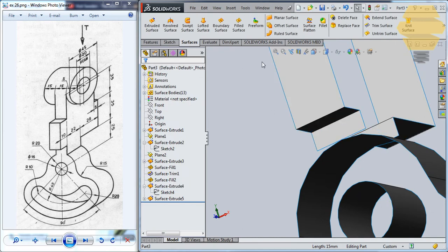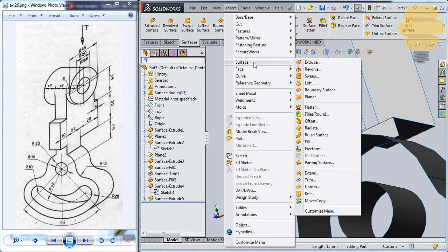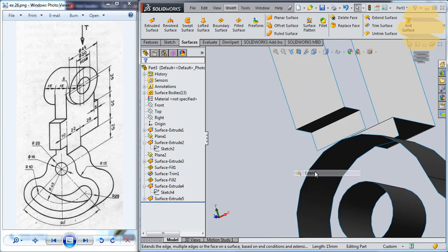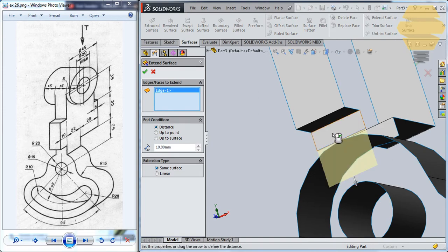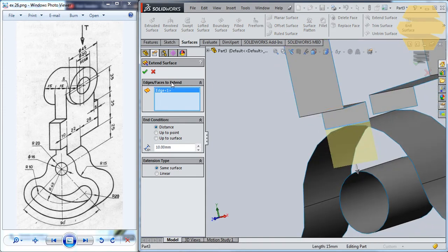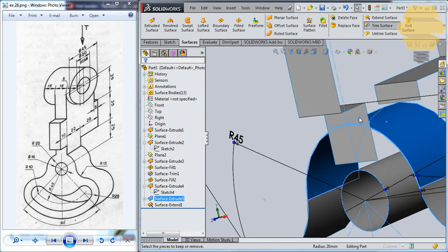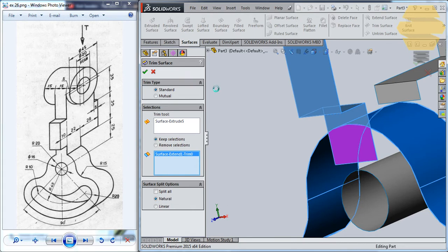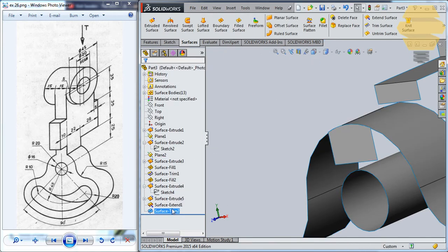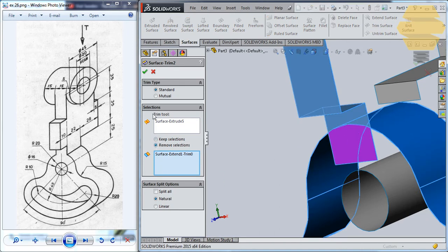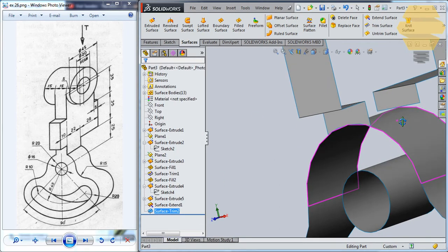No, not that. It could be in CATIA, it's called extrapolate, but not sure in this. What do they call it? Extend. Okay, that's an extend. Tick mark. Now we can select this surface, trim, take this portion off. Features, remove, tick mark. Now that part is done.